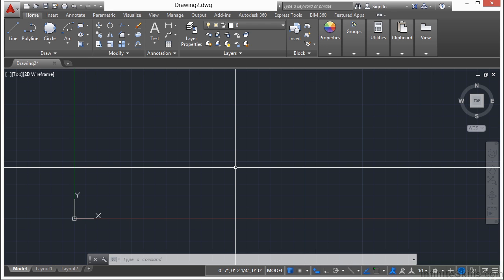Now, it's one thing to be able to draw lines and circles, but it's another to draw them accurately. O-snaps are one of the key features in AutoCAD that enable us to draw with precise and exact accuracy. O-snap is short for object snap. They force you to automatically draw from a specific point on an object. We've used several of them already, like endpoint, midpoint, or center, or even the nodes.